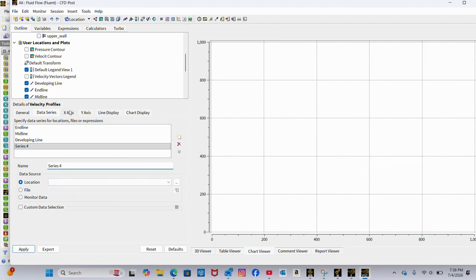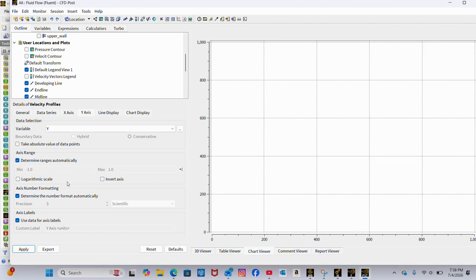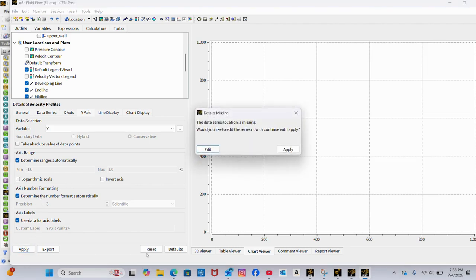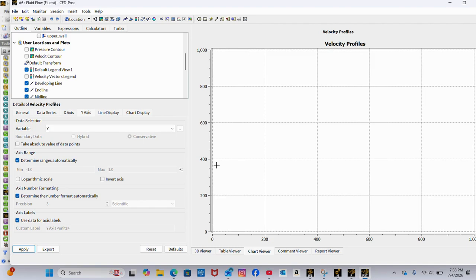You're going to do X series. You're going to make this velocity U. Y series, you're going to make this Y. And after that, you should just be able to go apply. Play. All right, so you got. We're actually going to change the axis range. We're going to go ahead and change this to 0. And we're going to change the max to 0.0001. We're going to play.